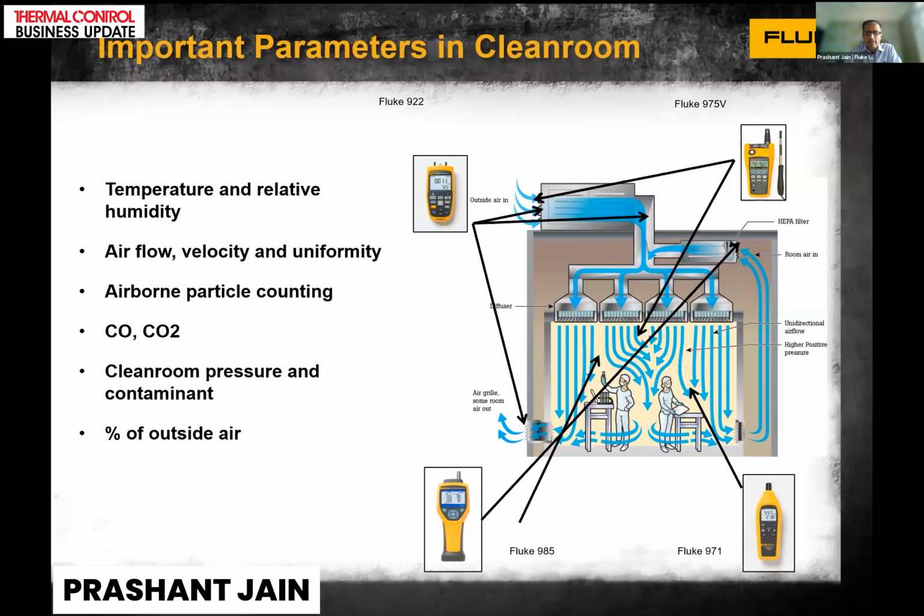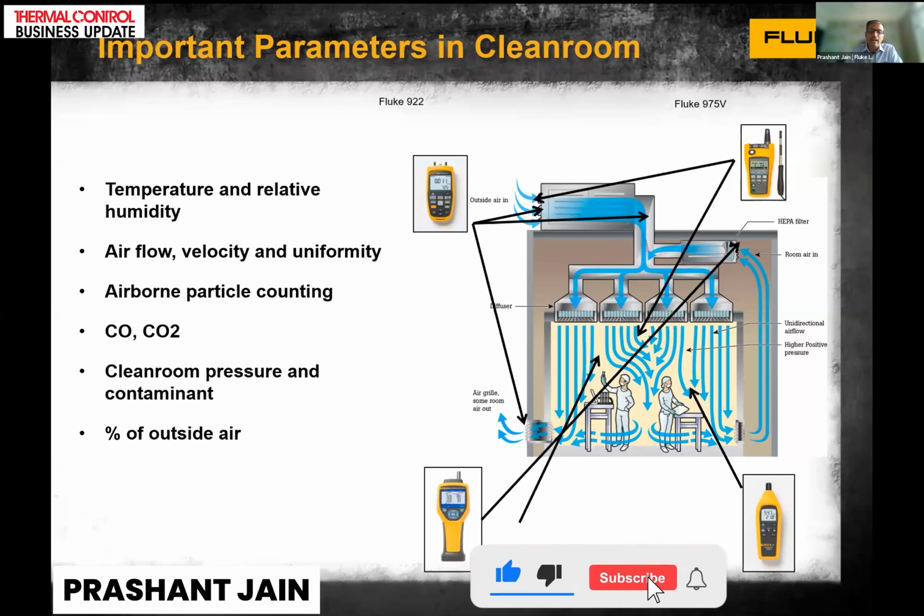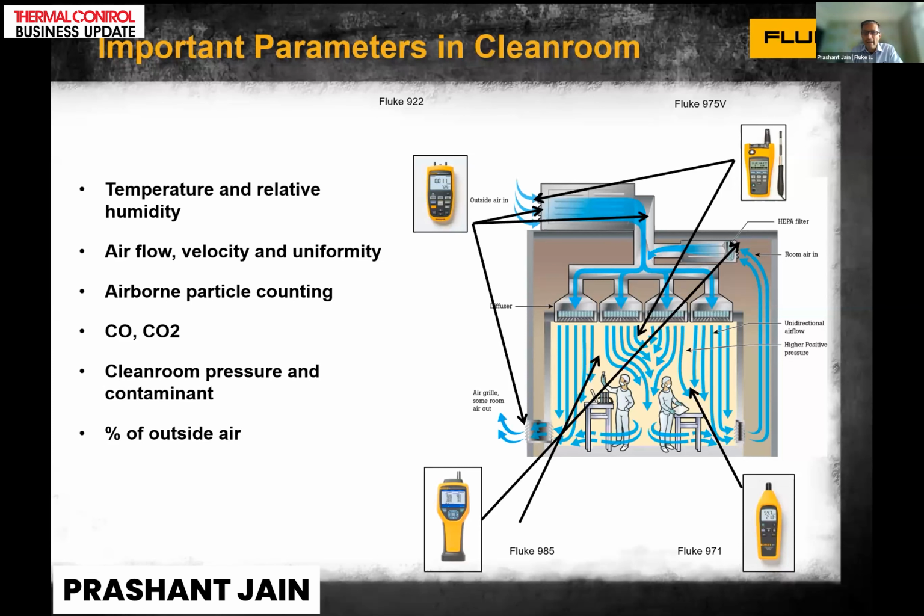We are at our offices or in our homes. If the temperature is within a range, something like 22 to 26 or 27 degrees centigrade, which is a normal occupancy temperature, we say that yes, it's a comfortable temperature. But if the temperature moves to 15 degrees, or to 20, or to 35 degrees, we feel uncomfortable. So for any building, the first measure is whether the temperature is in the acceptable range and the humidity is in the acceptable range. If the humidity is too low, we feel uncomfortable. If the humidity is too high, in that case also, we feel very uncomfortable.